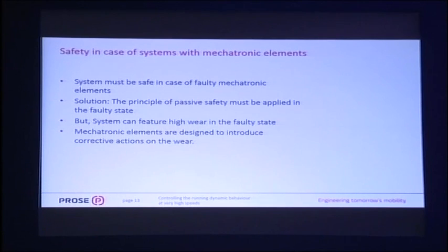So there is one big question: what's the safety of such a mechatronic element? It's very clear that such a system must be safe when the mechatronic element is faulty. So the solution is that in case the mechatronic element is faulty, you fall back to a passive safety state.